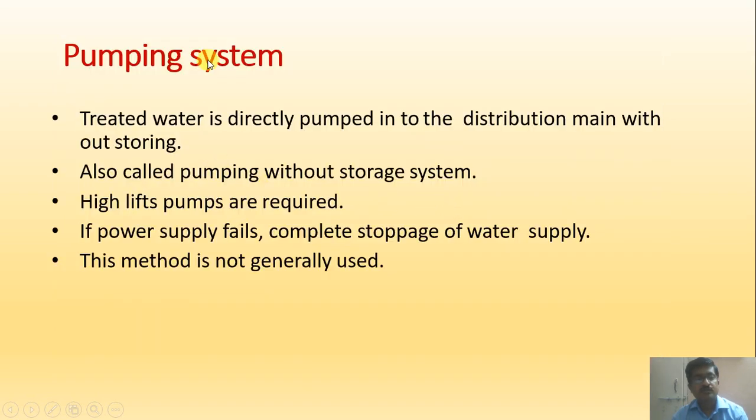Next one is the pumping system. Treated water is directly pumped to the distribution main without storing, also called the pumping without storage system. High lift pumps are required. If power supply fails, complete stoppage of water supply takes place. This method is not generally used.